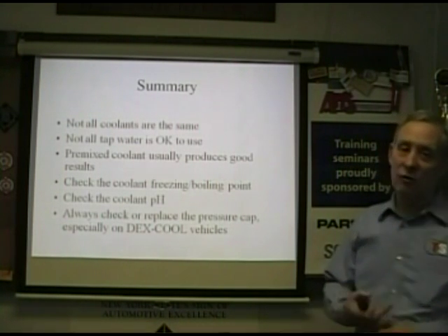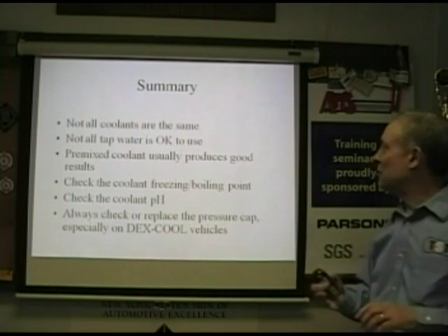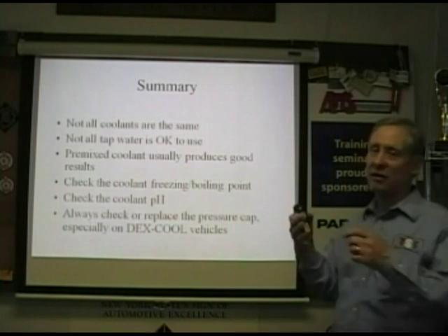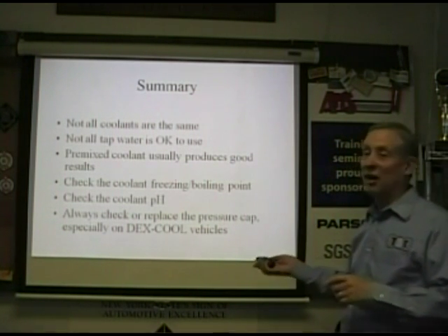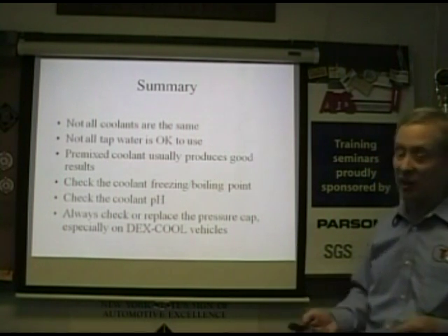Summary. Not all coolants are the same. Not all tap water is good. Premixed coolant usually produces good results. You got to check boiling point. You got to check pH. You got to check freezing point. And you got to check pressure caps. And it's not just Dexcool. It's everything, but especially on Dexcool vehicles.